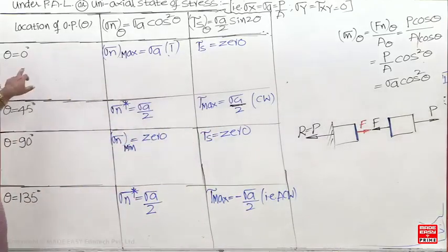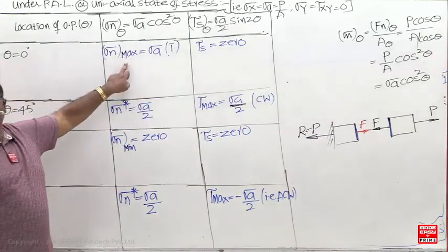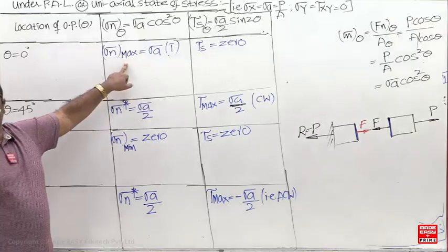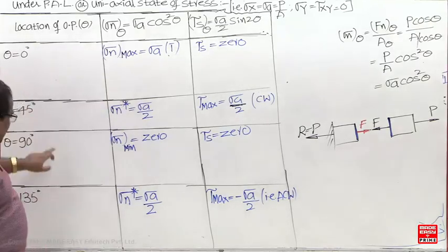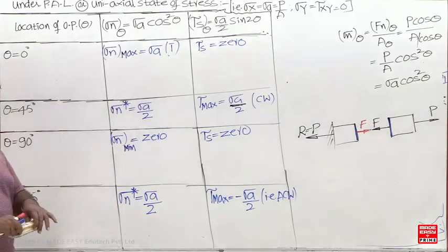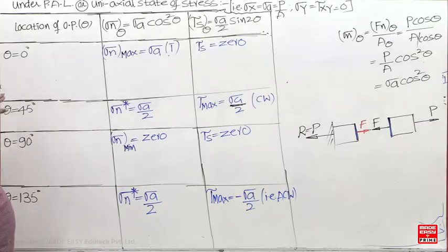But what is the significance now? The significance of this plane is that it is a fracture plane for brittle material. And what about these two planes? They are fracture planes for ductile materials. Now you can see, if I know one plane, can you get all these planes?